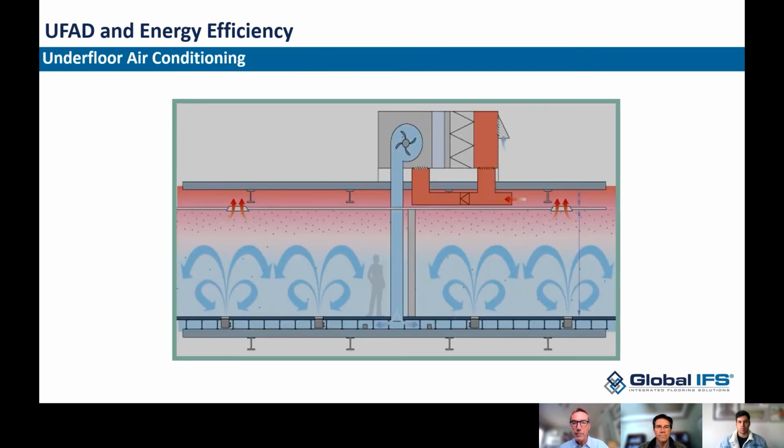The underfloor system, different paradigm, where we're looking to stratify, meaning we want to have two basic temperature air zones, if you will, in the space. So we're going to deliver that air through the same mechanical systems, but rather than through a network of ducts in the ceiling, it's going to deliver the air directly down, as you see there in the chase, into an underfloor plenum, or an underfloor space under that raised floor, which is essentially a non-ducted space.